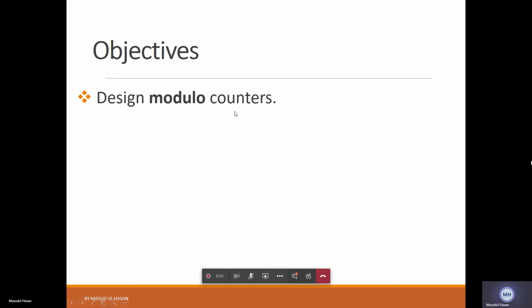Okay, now let us see the modulo 10,000 counter. This modulo 10,000 is what? It is calling 4 mod 10 counters, right? And you can see that I did not make the circuit for this. This will count from 0 to 9999, so it is counting 10,000 different values. And there are 4 outputs, 4 bits each, and one single output CO.